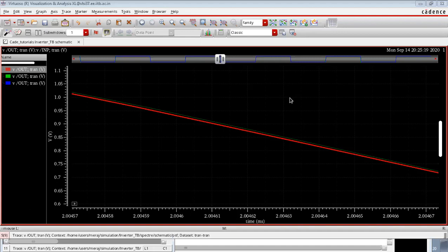So mainly for analog, it's a rigorous process we need to go through, and especially if you go to lower technology. What we have done, we did in 180 nanometer, but if you go to 65 or 28 nanometer, it's more challenging to design in that, considering all PVT variations. Because as your supply is reducing, your VDS is becoming very sensitive. All those parameters like gm, ro. So for low voltage design, you need to put more effort in design. That's where innovation comes.